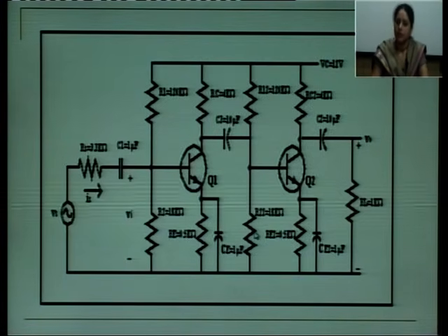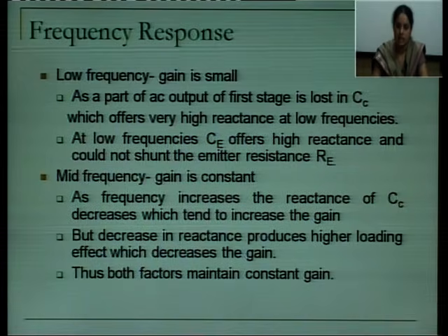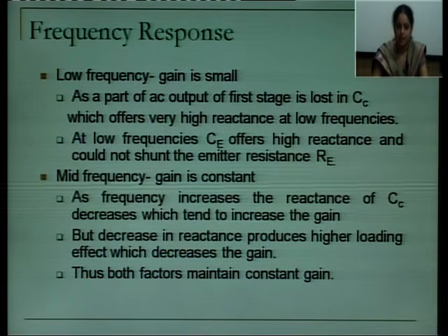Again, this is the circuit diagram of your RC coupled amplifier. Now coming to the frequency response, we have studied what the frequency response is. It is the graph drawn between your voltage gain and the frequency. Here also you have three cases of low frequency, mid frequency and high frequency. Considering these three different cases, at low frequencies the gain of your RC coupled amplifier is small.